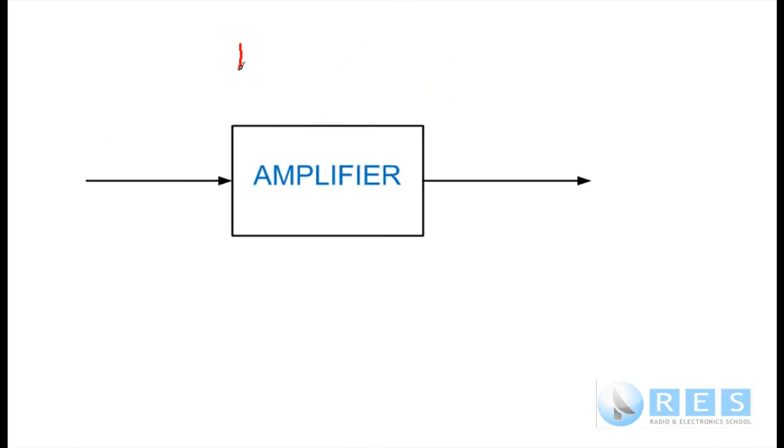Here we've got a non-linear amplifier. A non-linear amplifier distorts the signal that we put into it. We might put a full sine wave in and we may only get a pulse out. It creates a lot of distortion, and distortion is normally thought of as a bad thing, but in radio distortion is a good thing, or can be a good thing.